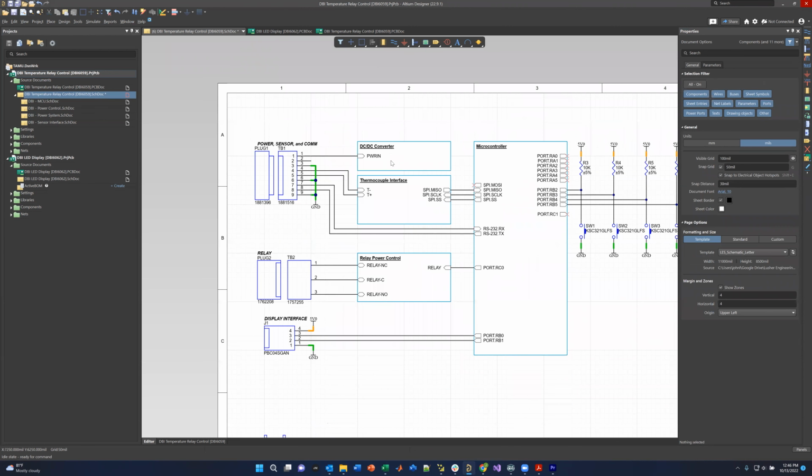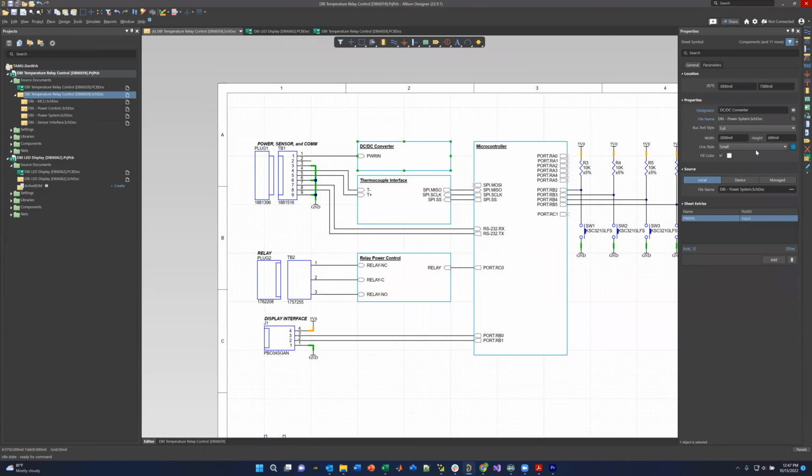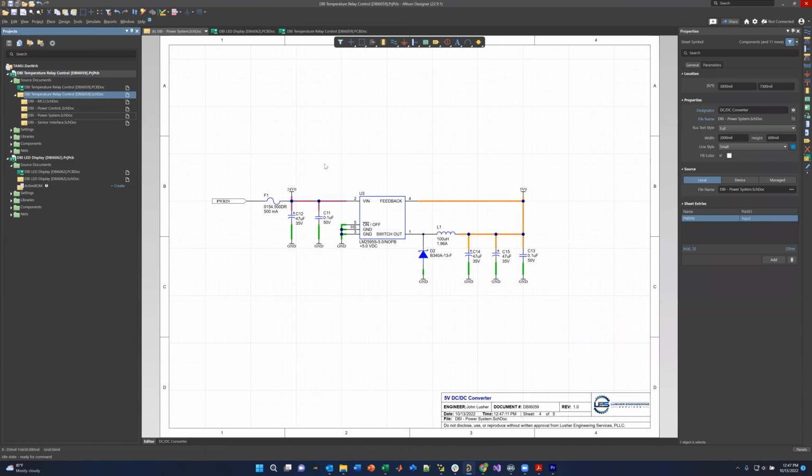These are device sheets. So when it compiles and it sees a device sheet, Altium, if you see on the left-hand side, will automatically make a hierarchical tree because it sees that this sheet is under the top sheet. So let's go ahead and take a look at this particular one. So this here again is power system.schematic doc, which is this file right here.